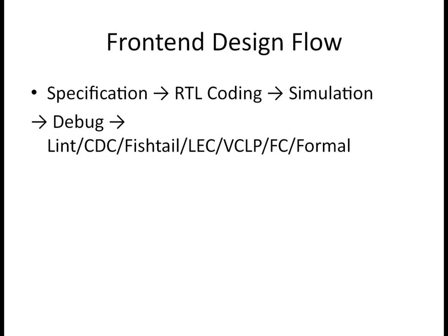And next is your LEC. So LEC is logical equivalence checking, where we'll be checking whether the RTL is correct or not. I mean, the RTL has to go through many cycles, starting from RTL design. It has to go through lint, CDC, Fishtail, synthesis.